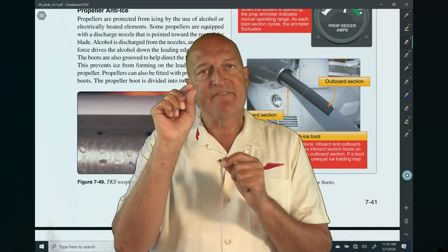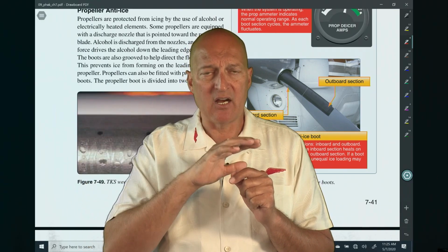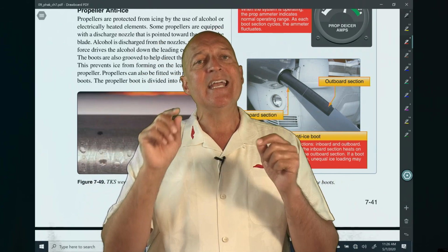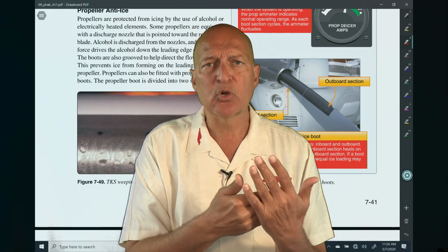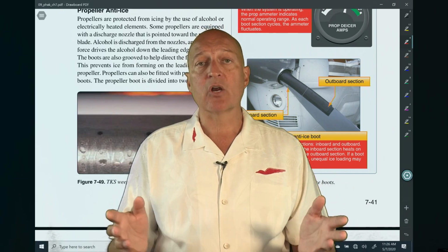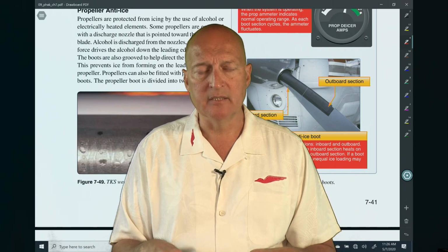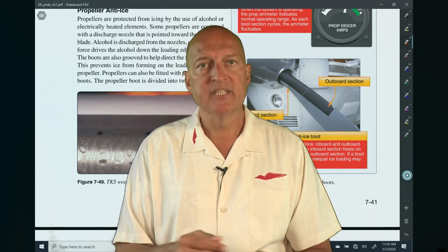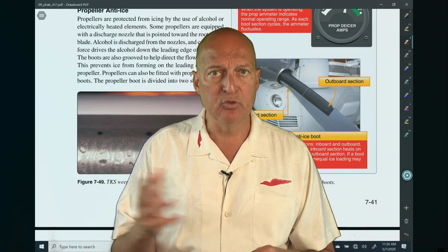And these systems have laser-etched holes on the leading edge of the aircraft. It can be on the wing, the horizontal stabilizer, the vertical stabilizer, anything basically that's going to be hitting supercooled water droplets that would tend to freeze on that wing anyway. The way these work, there are reservoirs where you put this glycol-based solution in tanks in the airplane. There's a pump, a series of pumps, and normally you have a high and a low setting for the pumps to move the fluid.